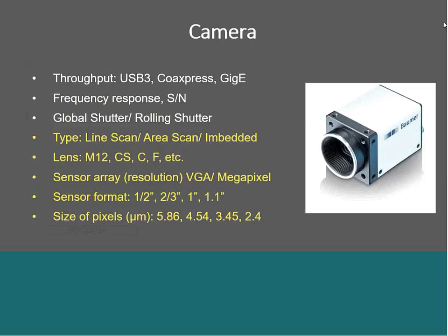So color cameras, every pixel looks at intensity. Color cameras simply put a color filter over the sensor so that they respond to certain colors. The principle is still the same. The size of the sensor array determines the optical format and to some degree the resolution. The optical format is the image sensor size. Many lens manufacturers will describe their lenses as megapixel, but we'll see in a few minutes, it's the size of the pixel within the matrix, not the number of pixels in the matrix, that really determines the lens resolution.